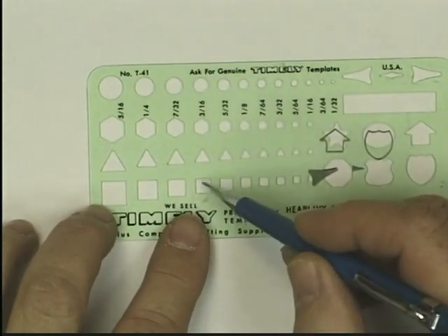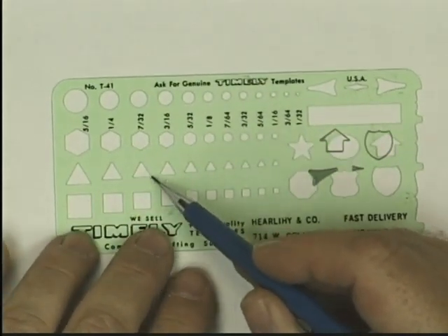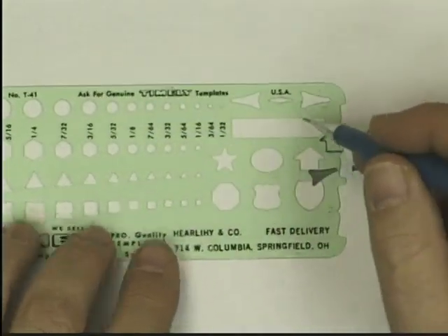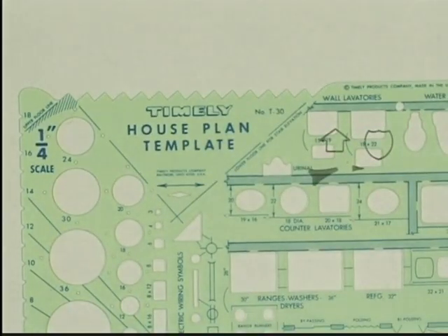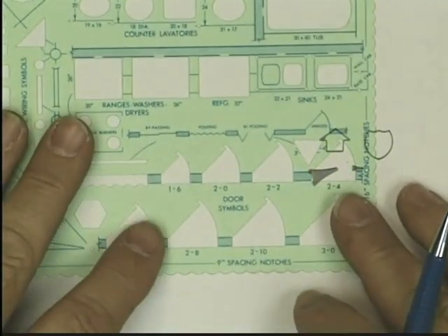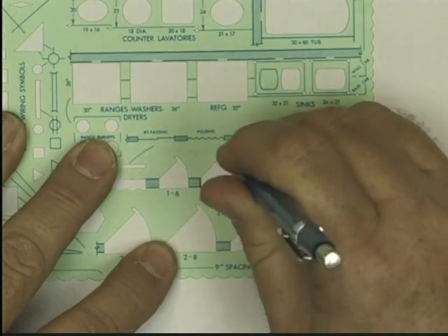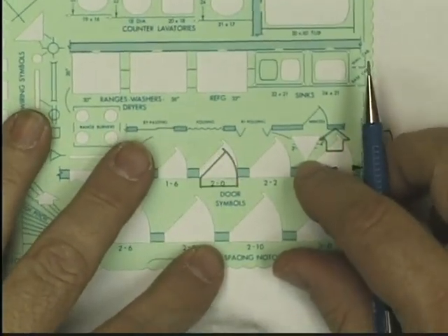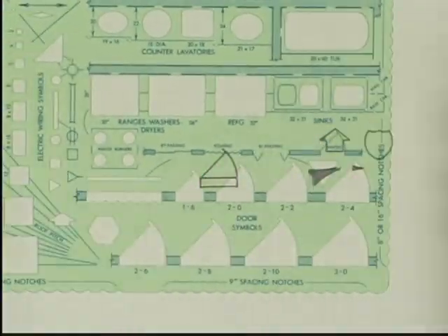It has circles, small circles of different sizes. It has hexagons. It has triangles, that is equilateral triangles, and it has squares. And so if I need to use any shape that fits this size over and over again, I can use this particular template. Maybe I'm in the house planning business. If I'm in the house planning business, I might want to draw door swings. And you notice there are a whole bunch of door swings here, and they're for different size doors. I can line that up, and I can just fill that in, and I'll use this thing again right there to show the wall thickness that door is filling in. You make door swings.